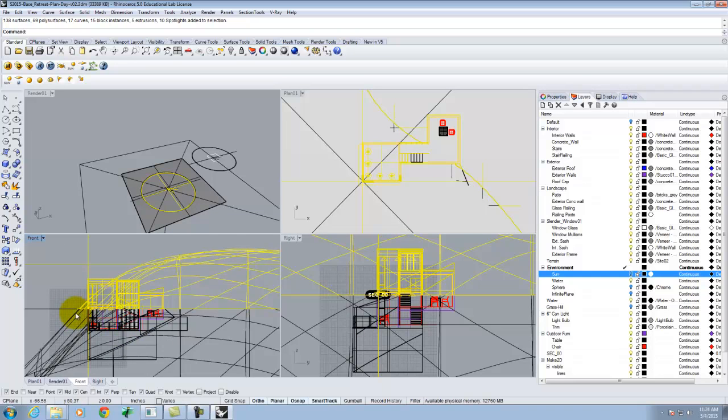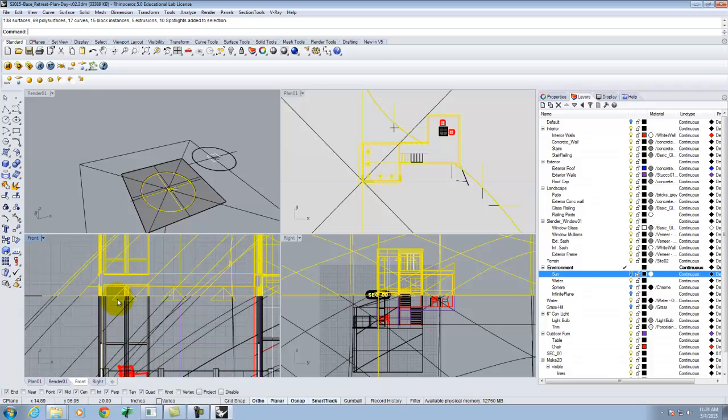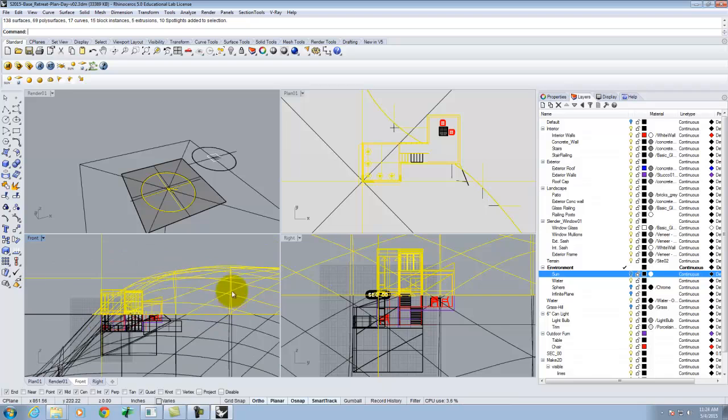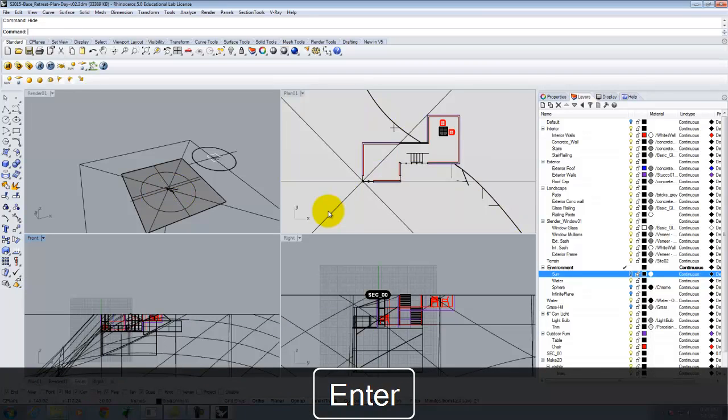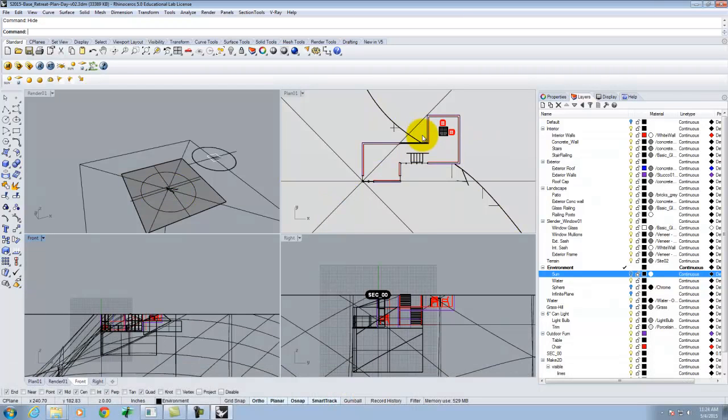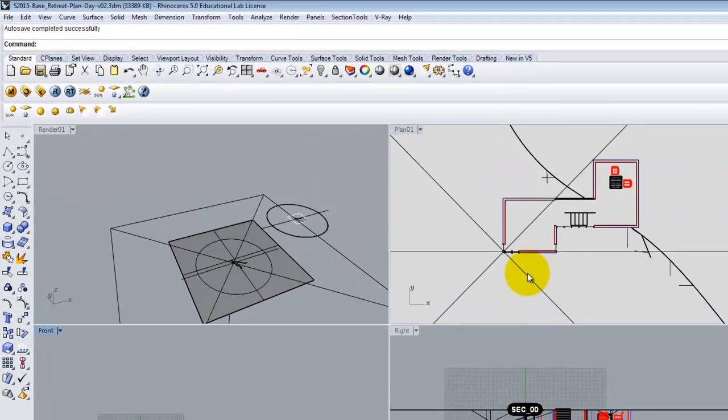All right, so I'm able to get everything, right? The lights, again, don't really matter. So I have all of that, right? And so the easy route is to just type hide once those are selected, and it makes that part of it disappear. Okay? And this isn't accurate for daylight settings, but it will give me a pretty good quality rendering.